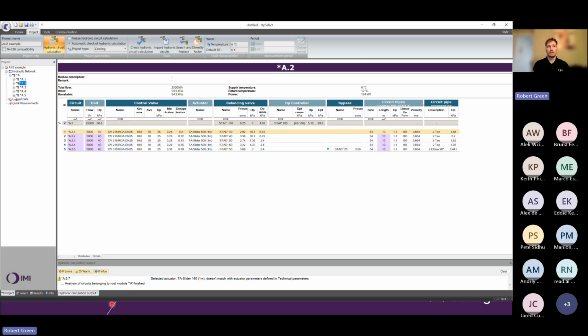What I would generally recommend doing, to correctly commission a system with diversity applied, is that realistically it needs to have at least some form of differential pressure control included. So in the example of this circuit, where we have 5 distinct differential pressure control modules, we would balance each module with that module being the only one online, using the differential pressure controller. We can then set the differential pressure controllers to achieve design flow with all of those units open.